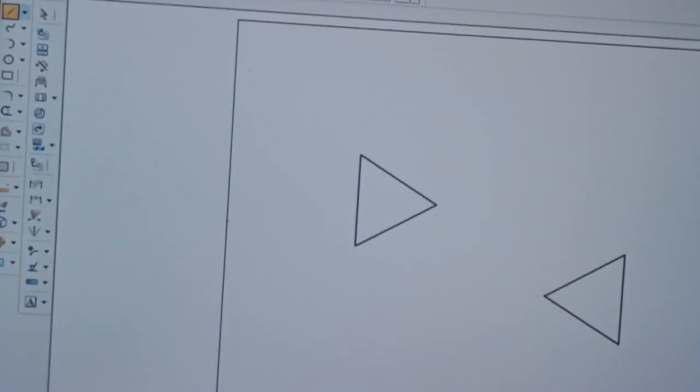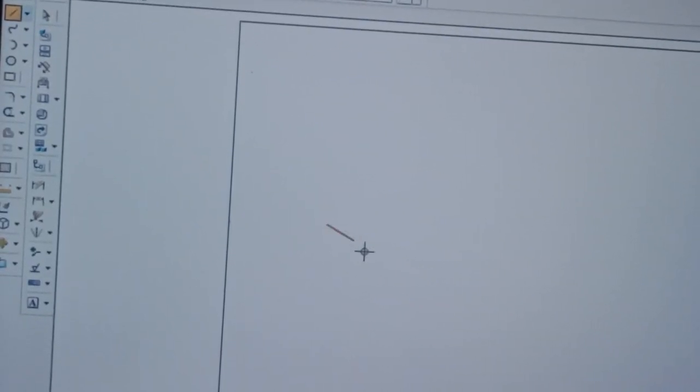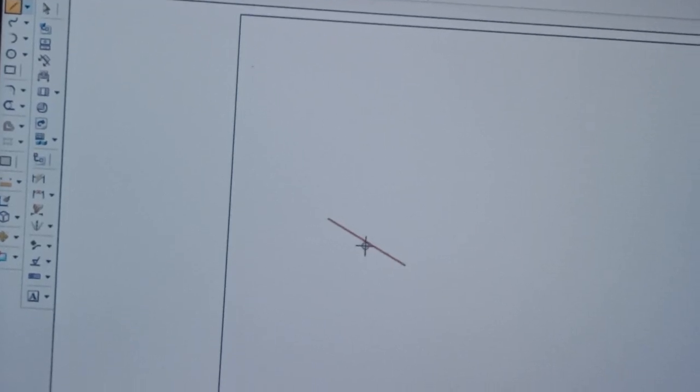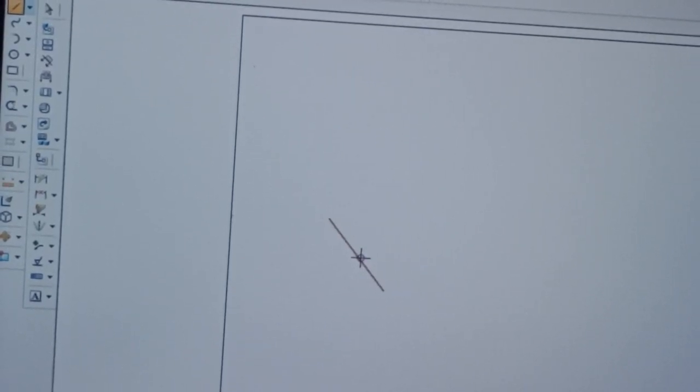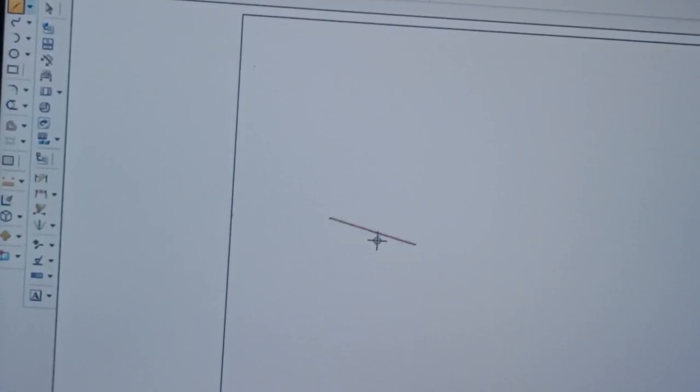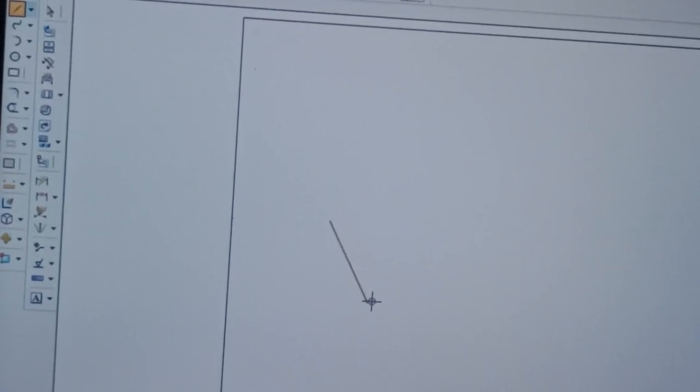So all of us are familiar with drawing squares. Now let's try to draw a square resting on the corner, with sides of 50 mm. The angle of the square is 90 degrees, so half of it is 45, and I want the line to come below. So I specify the angle as minus 45.